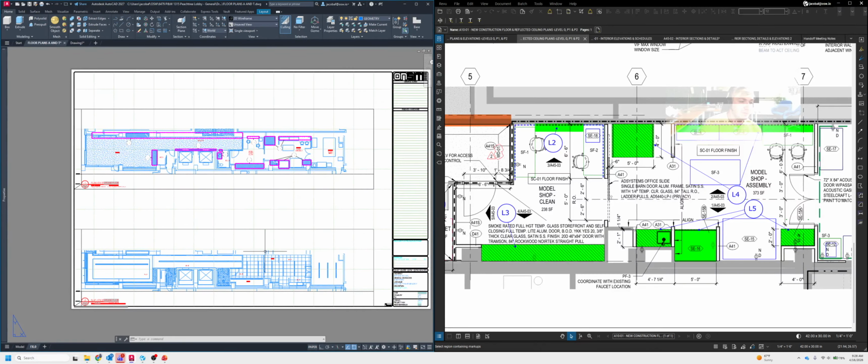And then the last step before you move on is going to be your tag here. Usually, if this was level 1, you would go A1.0, or if it's level 2, you're going to go A2.0 and so on. Whatever the floor is, that's the number there. So this is an odd one because this is the ground floor, so we're going to go AG.0 for ground. Okay, and then that's it.